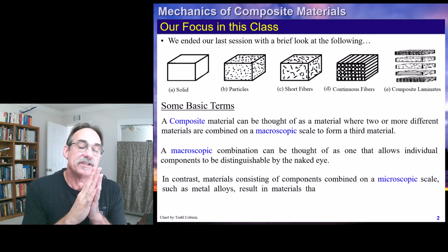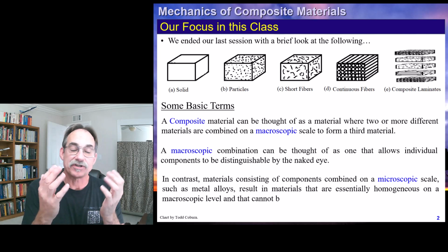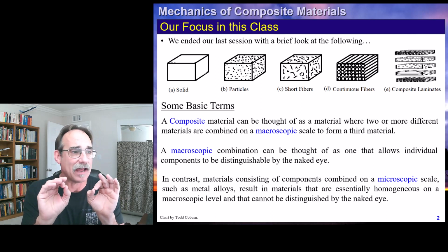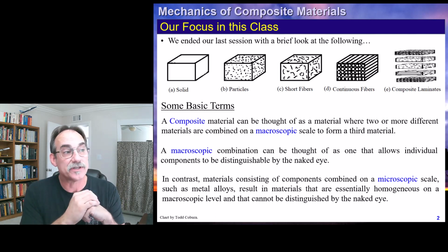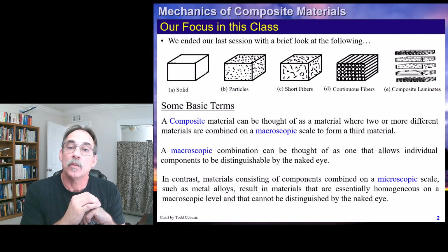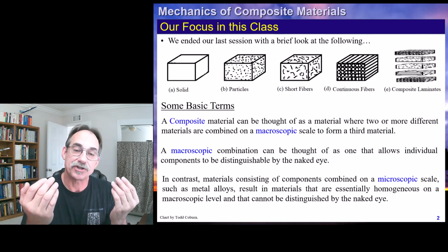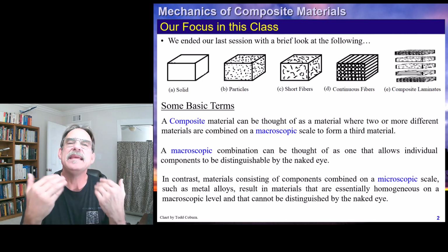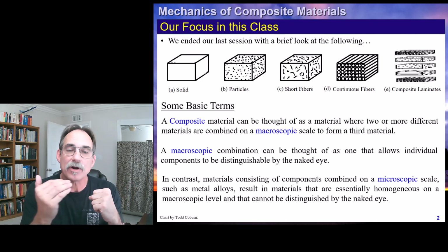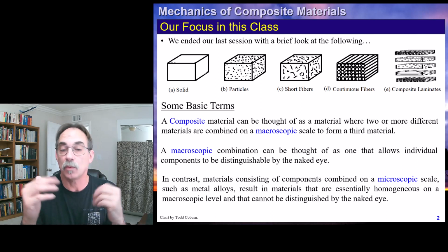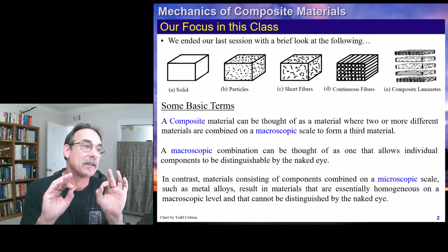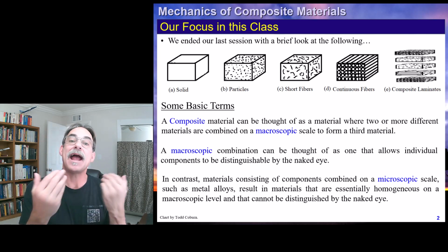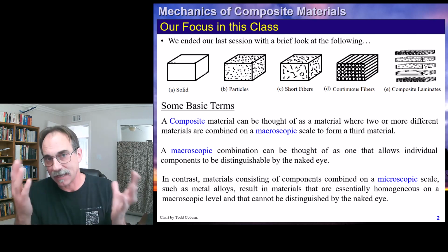This is in contrast to something that is microscopic. When we say microscopic, we could be talking about super tiny, but we're not really talking about that. For this continuous fiber element, element D up here, we have fibers and we have matrix. Certainly there is a much lower microscopic level at which we could view these pieces. What we mean by this term is we've got the fibers. We can look at what the fibers do on their own level; we're going to call that the microscopic level. How the matrix behaves on its own level, we can call its microscopic behavior. And then we're going to look at the macroscopic performance of the two acting together. That's how we're using those terms.